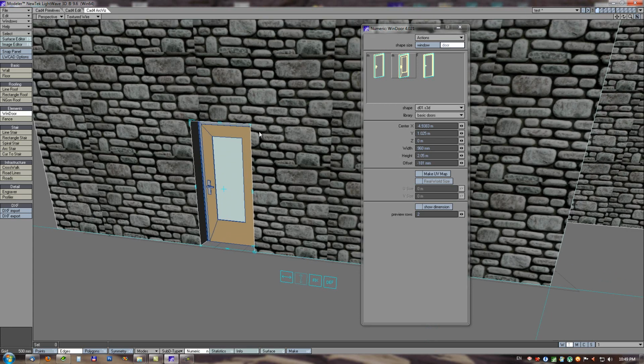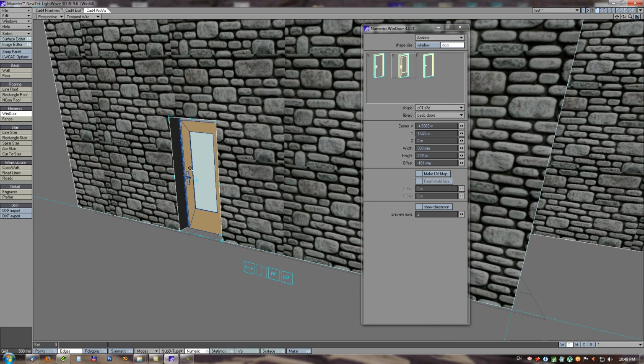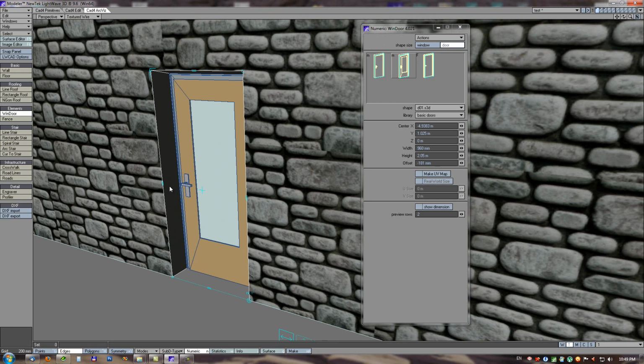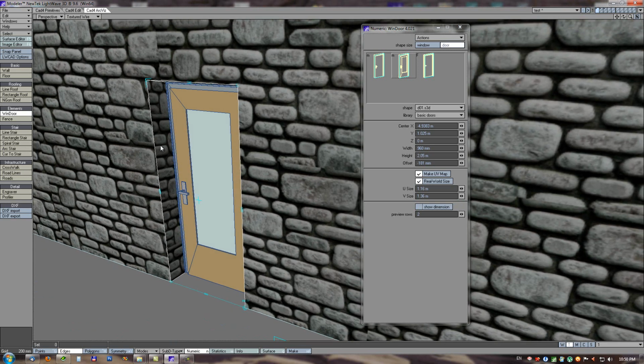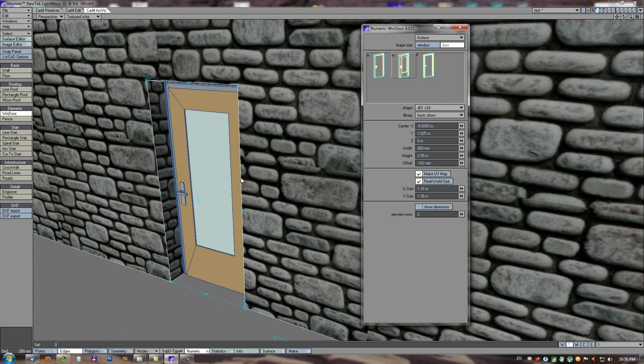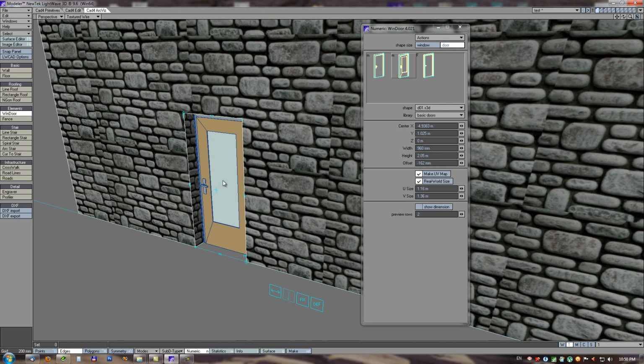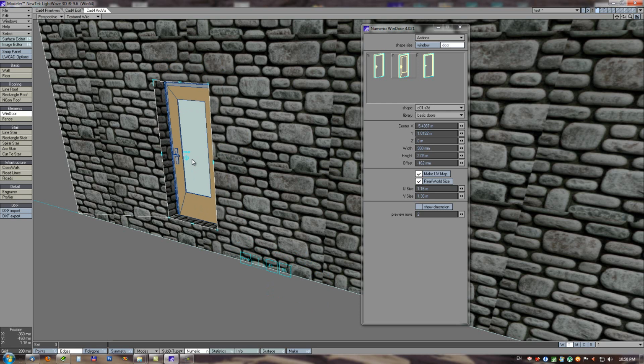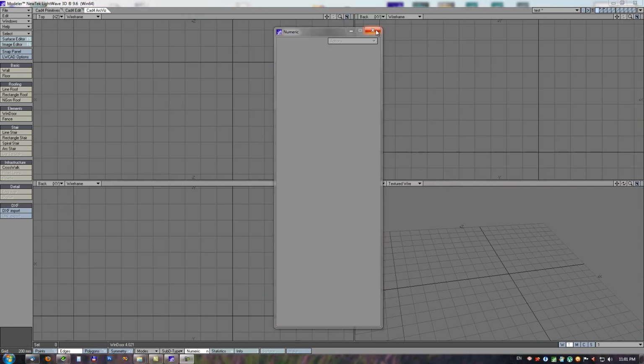And if we want to have this cut wall also UV mapped, just enable make UV map on this side and switch to real world, and we can also adjust these inside wall polygons which were cut. Offset mode is accessible only through the numeric panel now, because it was a little bit annoying to have it on the center handle. Okay, this is the window tool, a little bit streamlined.